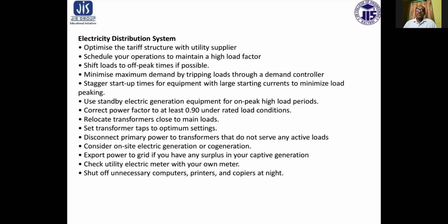Stagger startup times for equipment with large starting currents to minimize load peaking. Use standby electric generator equipment for on-peak high load periods. Correct power factor to at least 90% under rated load conditions. Relocate transformers close to main loads. Set transformer taps to optimum settings.